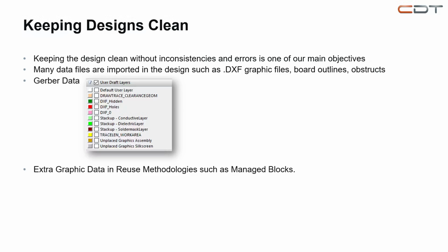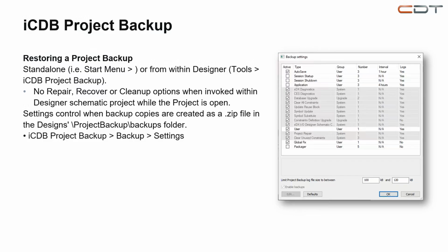There is also a cleanup tool in iCDB project backup, so you can use it as well, but it's a little bit different. It deletes the unneeded backups, log files, whatever was generated during the design process. If you faced a problem and you cannot fix the project itself, you want to try to restore the project backup. And a good thing to remember is that once you install the software, always first check the autosave settings or backup settings, depending on the context.